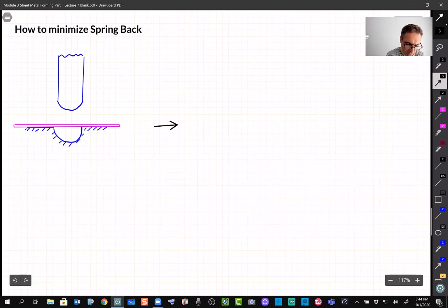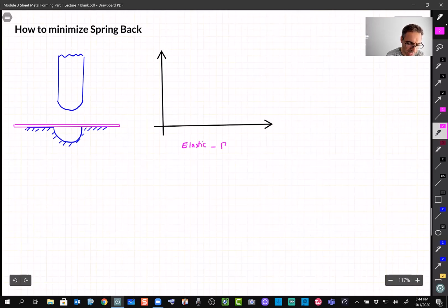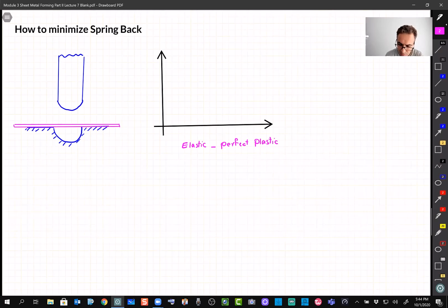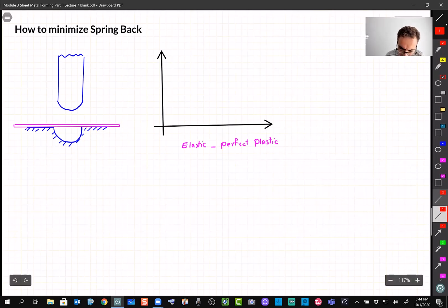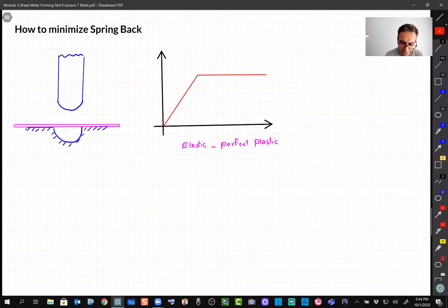There is a model which, again for simplicity, is called elastic perfectly plastic. I don't know why people invent all these weird names, but it's catchy. What they mean is, this is the elastic section, and then perfectly plastic, just a straight line. Somebody one day comes up and says, why do we want this curve? Let's simplify things, to estimate things.